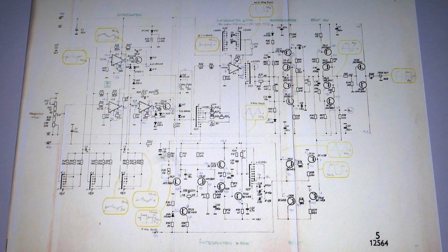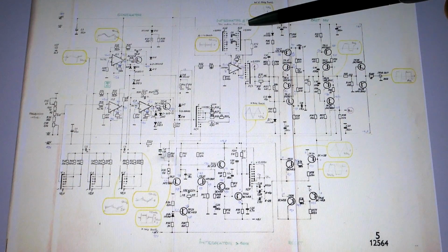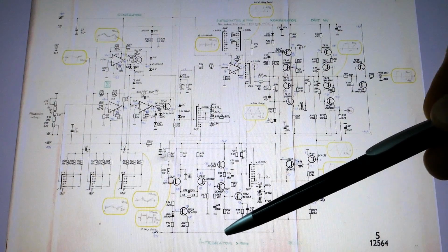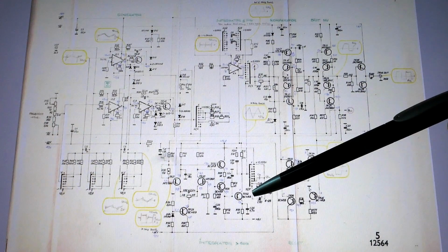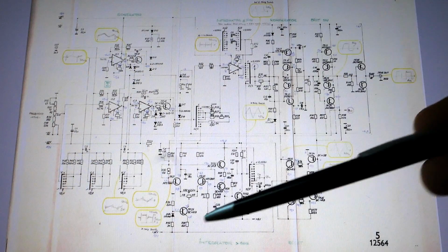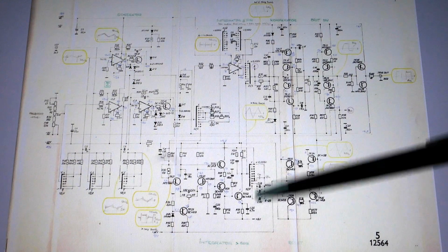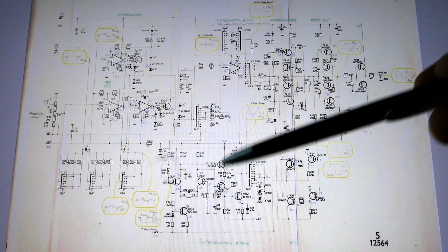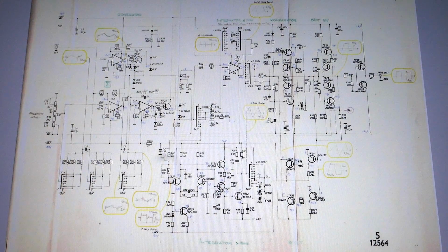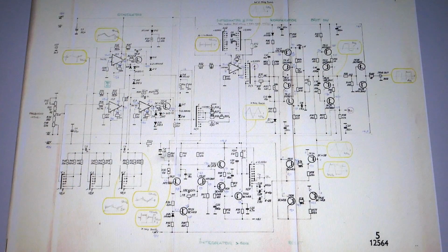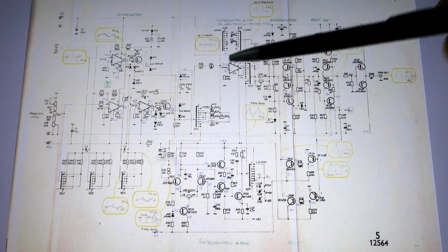But this op-amp is used in the integrator just for 1 kHz or lower ranges, but for the highest frequency ranges above 1 kHz, which is basically the top two ones, 10 and 100 kHz, it's doing the integration not in this op-amp but in this transistor contraption, probably because the op-amp is too slow for it, and because it's using two different integrator circuits for different ranges, and the distortion happens in all ranges, we can simply rule out the entire integrator circuitry, both of them, both this discrete integrator and this op-amp based one.